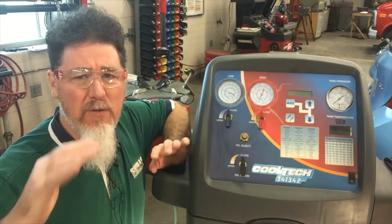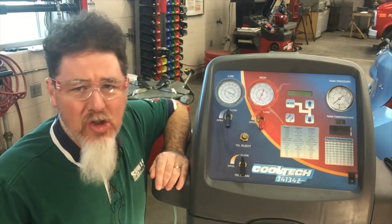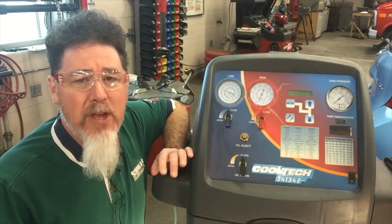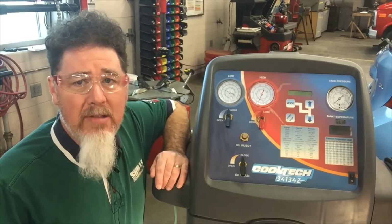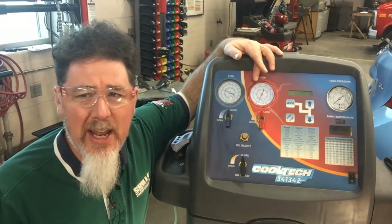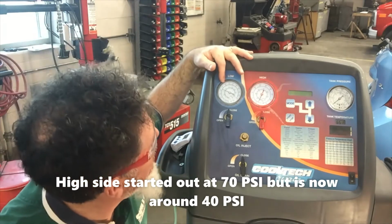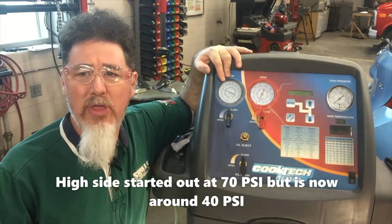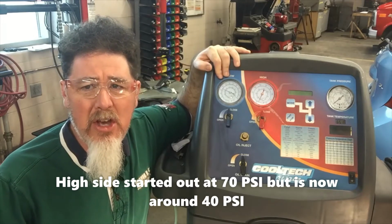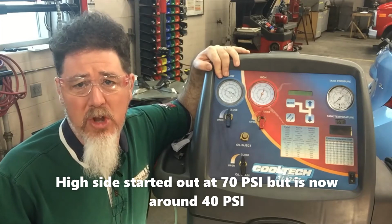The AC lines, when you feel them, nothing is hot, nothing is warm. The suction line feels a little cool, maybe a little cold, but definitely not normal temperature range. Looking at the pressure readings, the high side pressure is 65, 70 psi. The low side gauge reading is around 35 psi. I think most technicians, when they would see this, would think it was an undercharged system, and they would recover to see if it was low charge.